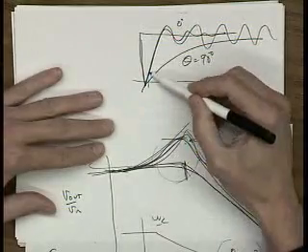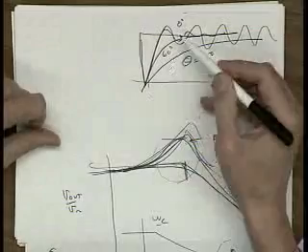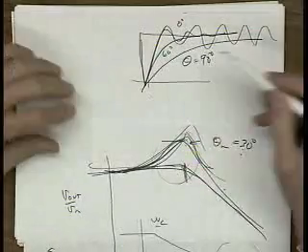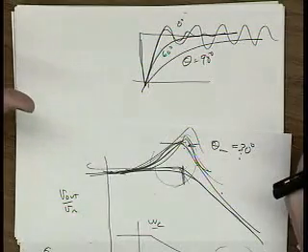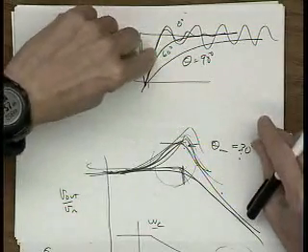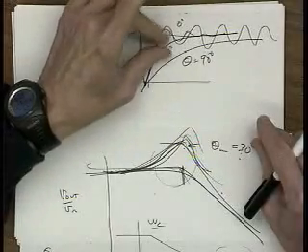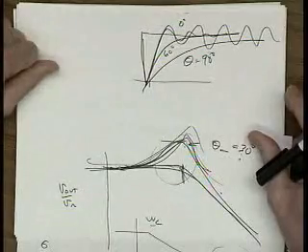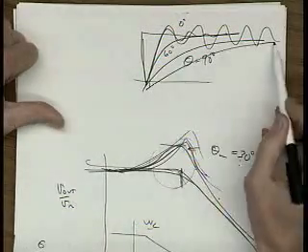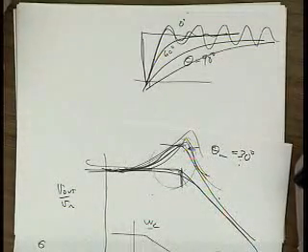I don't know, the critically damped thing is like 60 degrees or something like that, I think, or it gets up as fast as it can and doesn't ring. It doesn't hurt to ring a little bit. It doesn't hurt anything. So playing with phase margin, you will be able to adjust, in some sense, how much ringing you have here, and that'll help a lot on your settling time response, right? Settling response. If you get too much phase margin, the thing's stable, but then it just rises really slowly. Right?